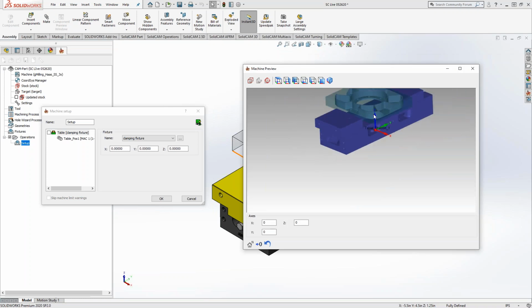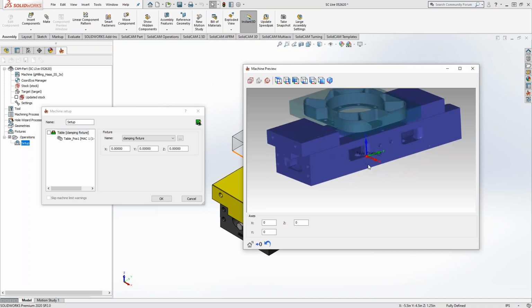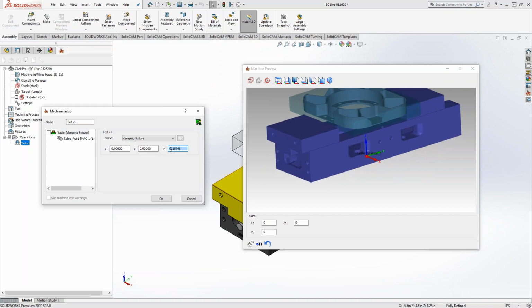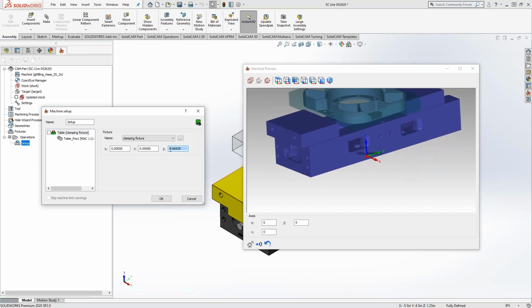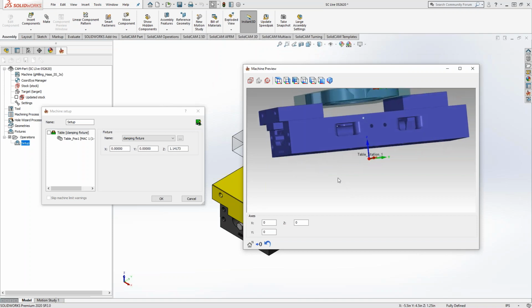Okay, so there's my table 0, my Mac 1, all of that is sitting correctly. The fixture mounting coordinate system is over top of that. Let's do an example of how far away the fixture needs to sit from the table. Let's say for whatever reason there's a spacer there, that represents that distance. So this is the machine 0.